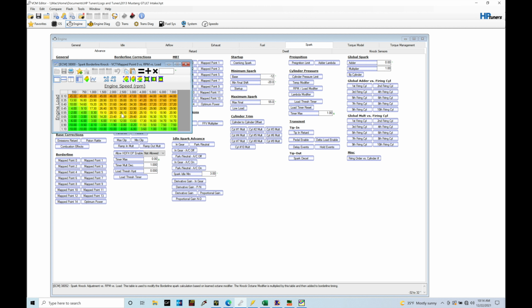Now, we're going to be starting off at 0 degrees of engine rotation when the engine is starting into the intake stroke. That's where the intake valve is going to open. It's going to allow air and fuel into the engine. The piston is going to draw its way downwards towards bottom dead center, or the bottommost travel of that piston movement. And there, we're going to call that 180 degrees of rotation of the crankshaft.